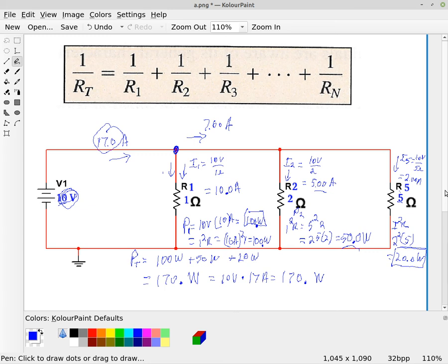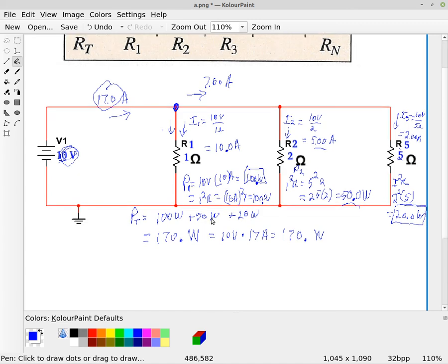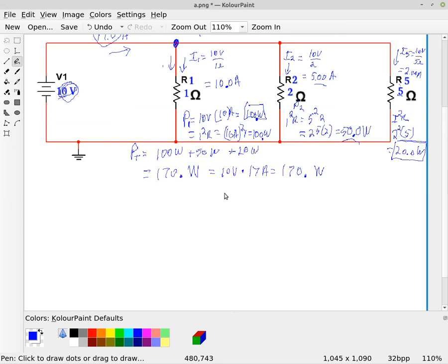We see up here at the top I have the equation for resistors in parallel. The way you would punch this into your calculator is you would take your resistor 1, so you'd take 1 and then hit the -1. Most calculators have a -1 button. So you'd hit 1 to the -1 plus 2 to the -1 plus 3 to the -1.